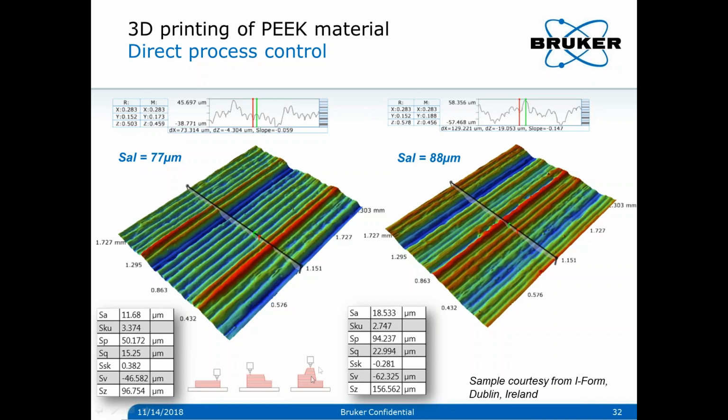Basically the PEEK material is extruded too hot and starts to melt further down, creating issues on that surface. So in that case, when dealing with very rough surfaces, focus variation can directly extract parameters linked with the process. You can define an experimental plan and find the best parameters through iterations, getting this mean correlation length plot.